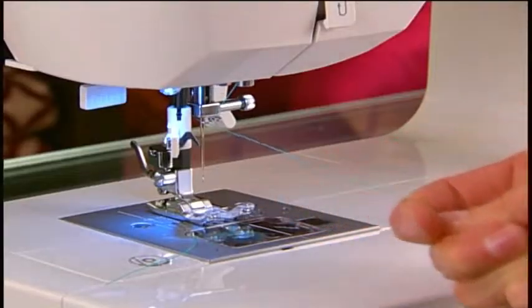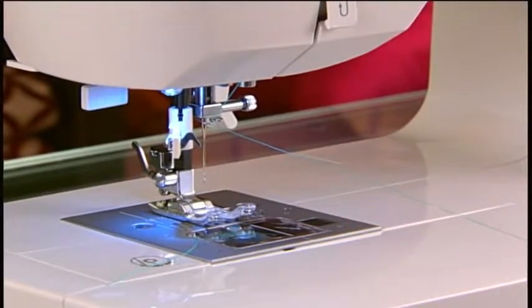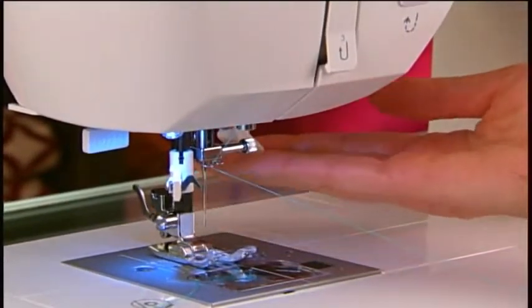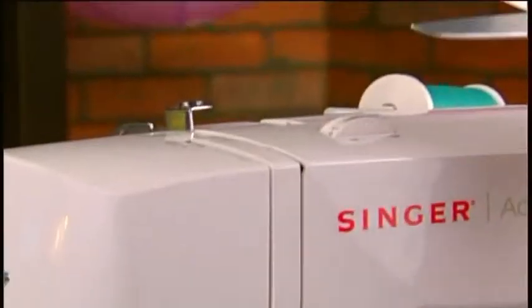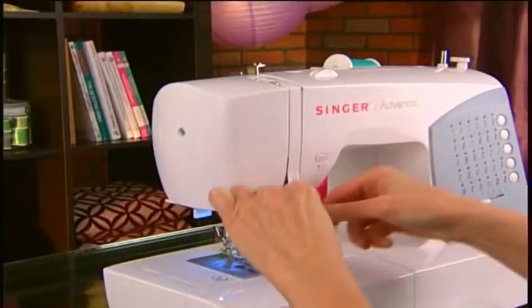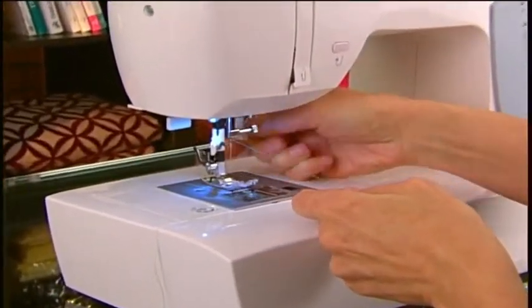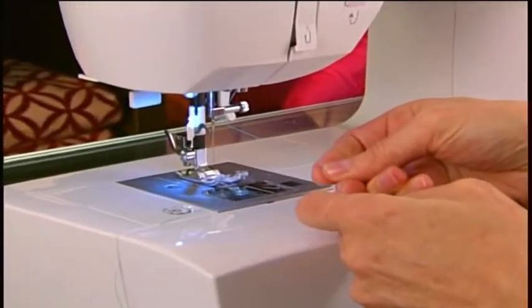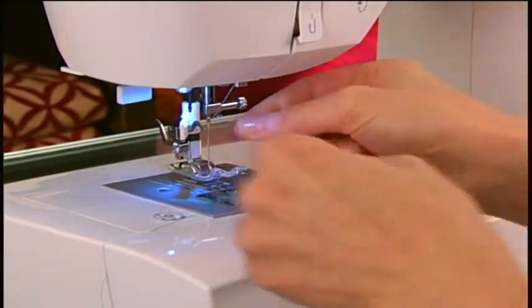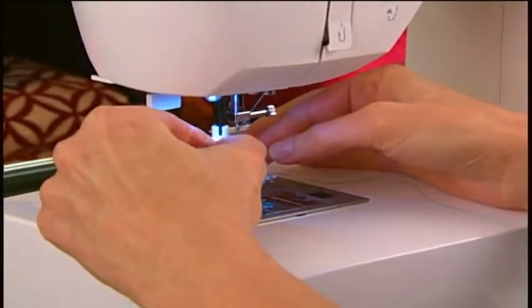If you are still able to pull the upper thread freely when the presser foot is down, this is an indication that the tension is not correctly threaded. Raise the presser foot and then completely remove the upper thread. After you have rethreaded the upper thread, put the presser foot down. If you do feel a significant difference in the tension when you pull the thread, you are now ready to thread the needle. Raise the presser foot, thread the needle, and sew.